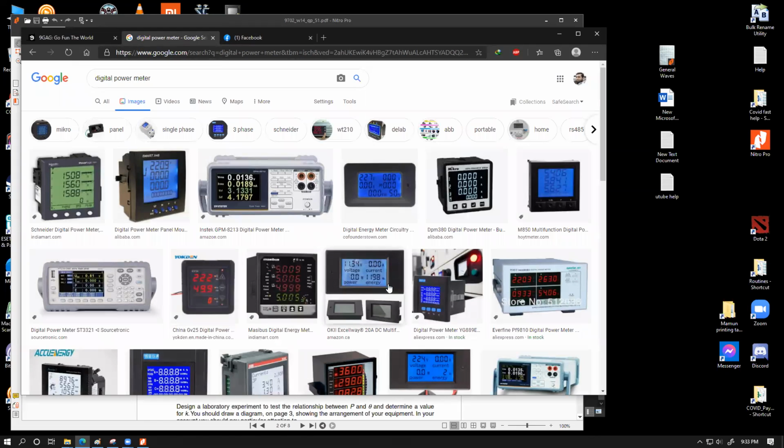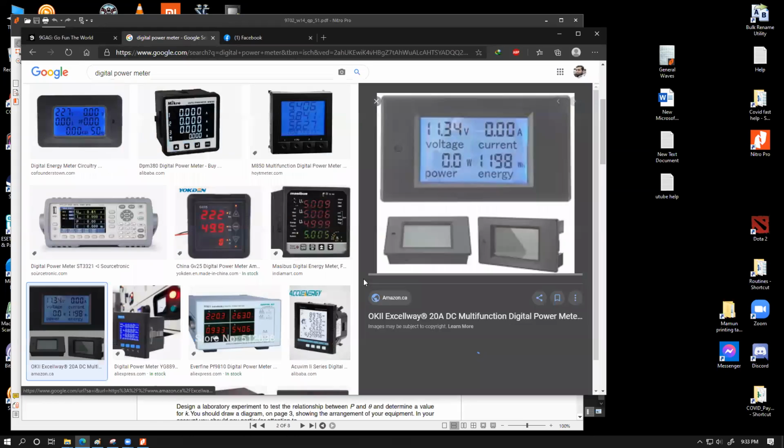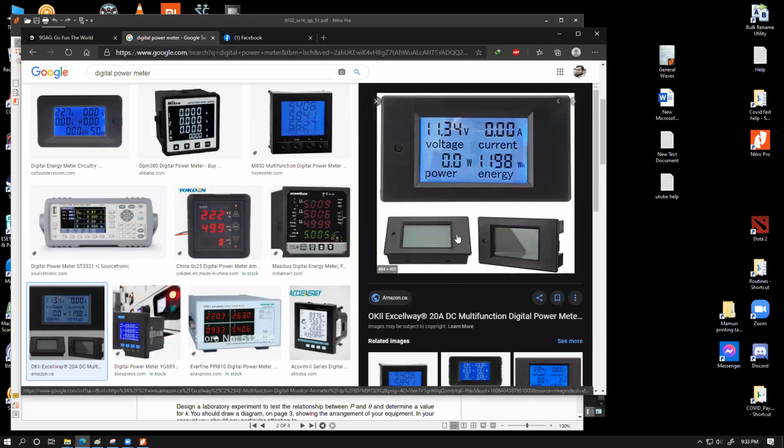There you see. So this is the thing that I was talking about. There are certain electronic devices which actually have built-in ammeters and voltmeters, so you have a certain voltage they measure by the voltmeter. You have a certain current. For this, currently there is no current in this display, that's why the power is 0. But any single time, if there is no zero error, then the product of these two variables should be equal to this one. So if you have this device available to you, then you might as well get the power directly out of the display.